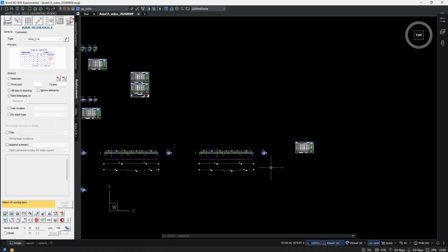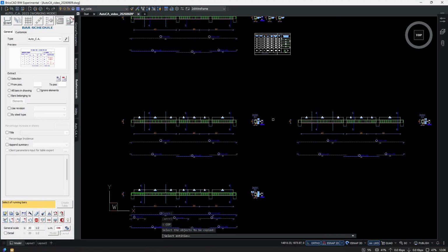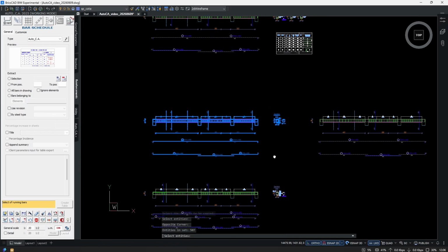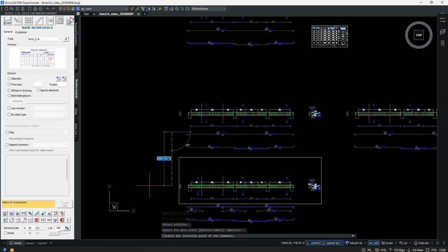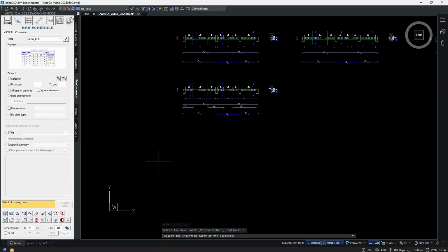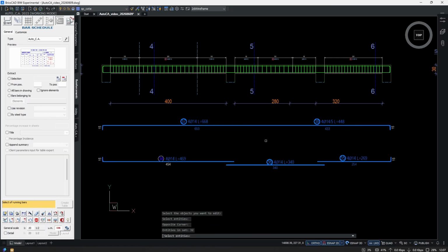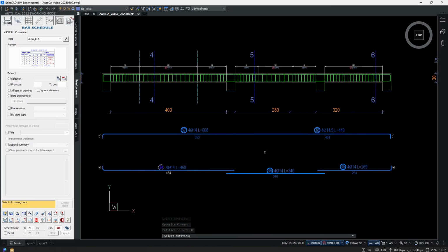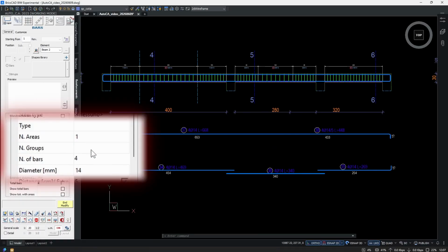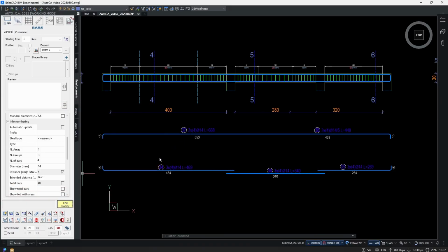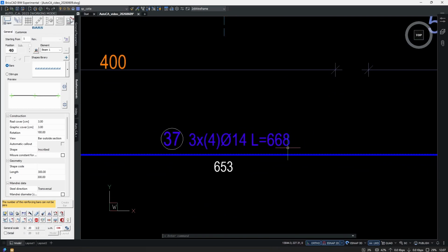And there's another way to do the same thing, which is maybe the easiest way, is to select another beam of which you have multiple ones, and enter into the modification panel first for the longitudinal bar, and here in the group numbers just type in the number of how many beams you have of the same dimension. So for example, I type in 3. Now we will have modification in the labels of the bars.